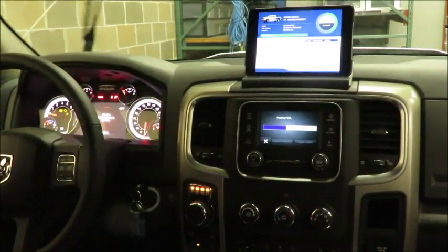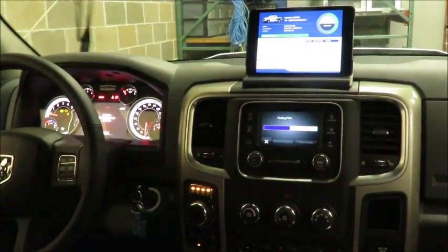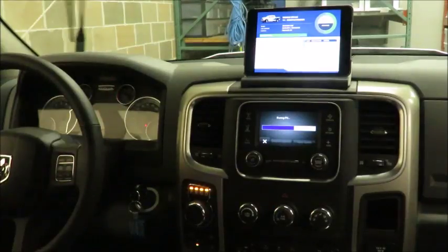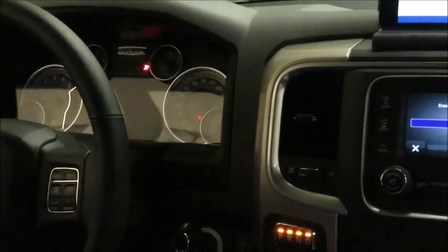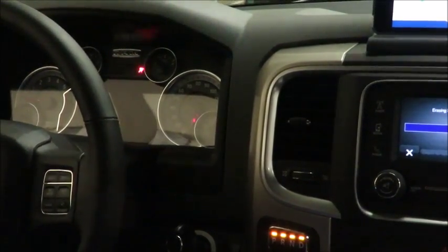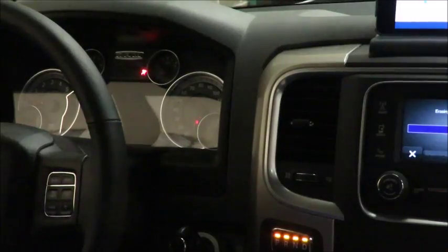For this vehicle, due to the quieting of the CAN bus, you will notice the wipers will turn on. This is due to the fault mode analysis of the wipers, which states if it does not receive communications from its rain sensors, it may be raining. Thus, for safety, the wipers are enabled.